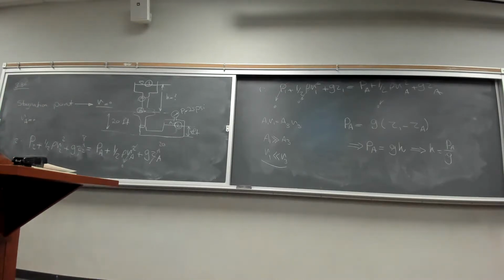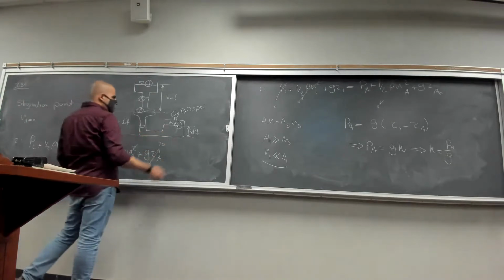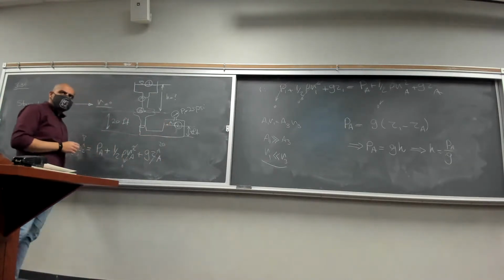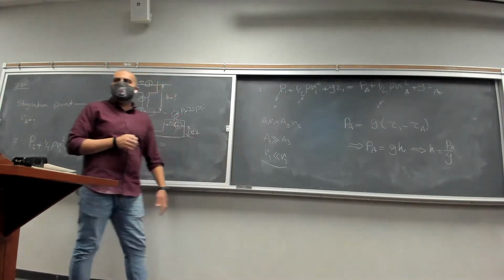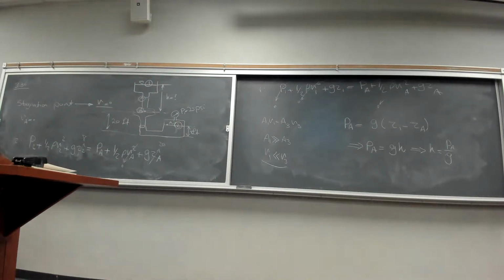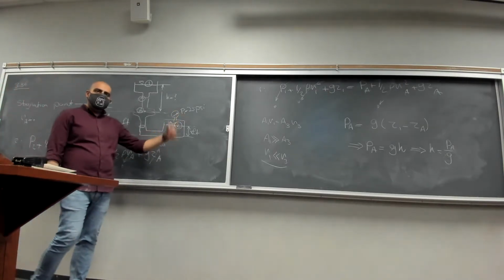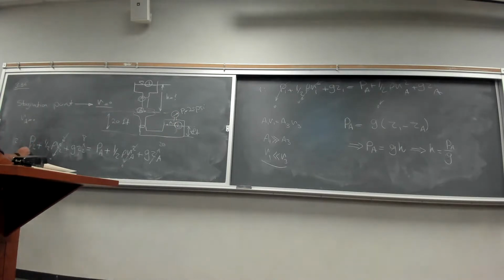What about the velocity at point 2? What can we say about the velocity at point 2? Here, on this air surface, we can apply the same analysis we did here. So we can safely assume the velocity at point 2 is also 0. So this will cancel out. And P2 is going to be the pressure you're reading at this gauge, 25 psi. Okay?